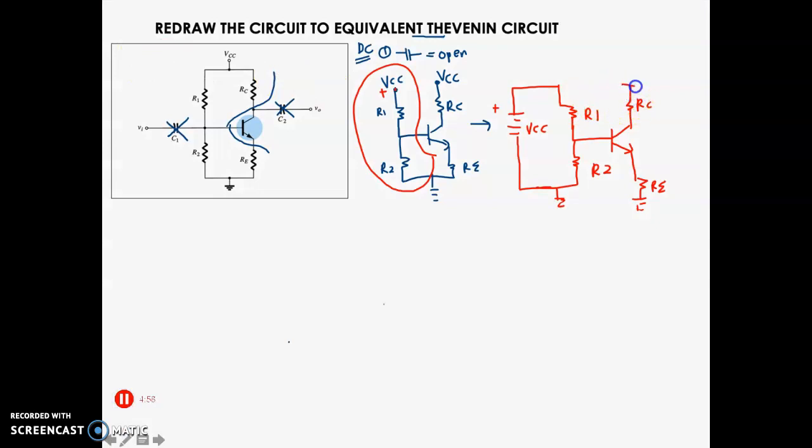The above one will be connected to your VCC. So what you need to do now is change to Thevenin at the connection at your base. If I restructure the circuit, it becomes R2, with R1 connected to the other side, and this is connected to your VCC, and then the whole will be ground.